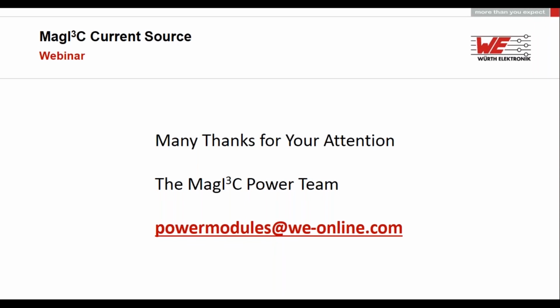Because as we saw in the graphs, the transient response, I used the signal generator and adjusted a rectangle waveform. But in general, you can use an arbitrary waveform of your choice. So as far as I know, you don't need an extra charge controller, because you have everything you need to charge accumulators. The functions which are not implemented if you use a power module with a current regulation are, for example, monitoring the temperature of the batteries.